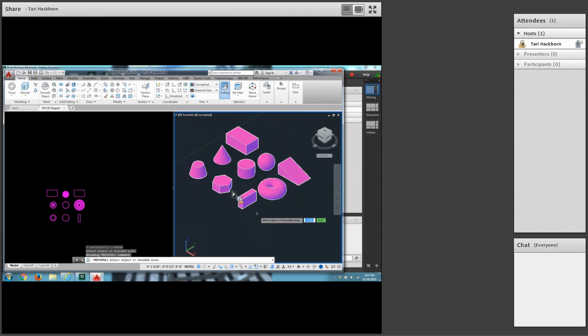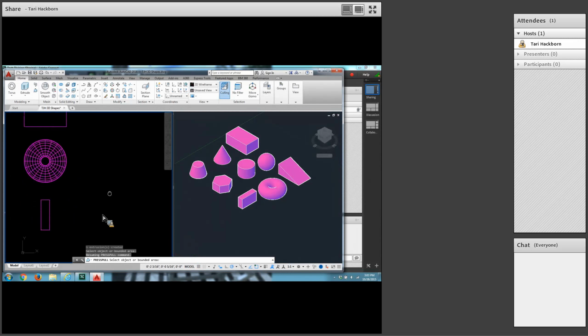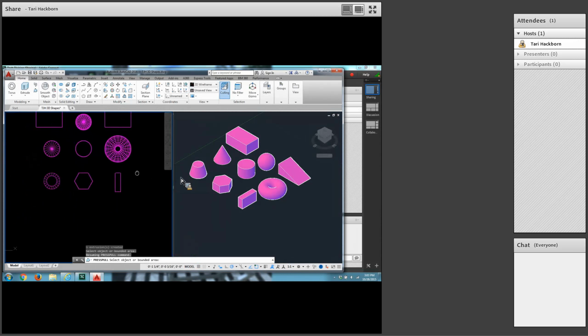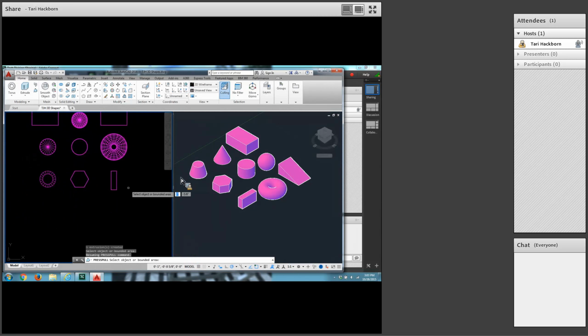The next thing is to draw an extruded structural angle. It's best to start this one over here in the top view, so I'm going to click to activate it. At the bottom of page 54, it says to select the line command and start at 1, comma 3. Line command 1, comma 3. And to go at 7/8, comma 0.